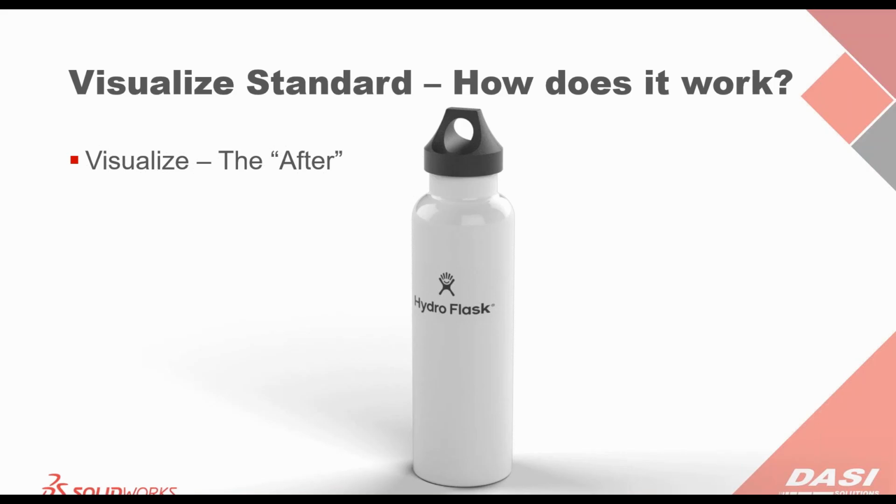And this image here, the other question I wanted to address was how long does this take and how many passes? This one I tweaked and I applied some more appearances to bring it to life and play with it, but I think this only took about 6 to 7 minutes, and I put it at around 500 passes and it looked great. So more than enough passes in this case to create a quality image. You could always bring it up to 1,000 and it won't increase your rendering time that much at all.